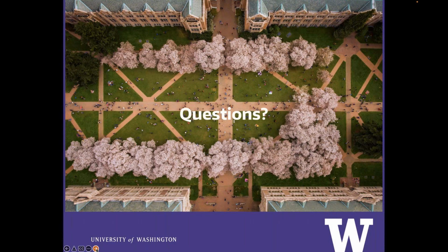You mentioned you almost closed with that ring for improvement of behavior. When should the engineer designer consider that? When would you recommend it? We haven't been able to test this, but my recommendation would be that unless your pile to column diameter ratio is 2 or more, I think the ring is going to give you better response.